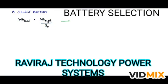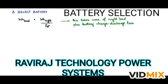the battery will see to it that it supplies sufficient amount of energy for the load. This efficiency factor here is included to take care of charge discharge losses. So this watt hour night by efficiency will take care of the night load plus the battery charge discharge losses that we have already discussed. Now this is if the PV panel participates in supplying to the load every day.